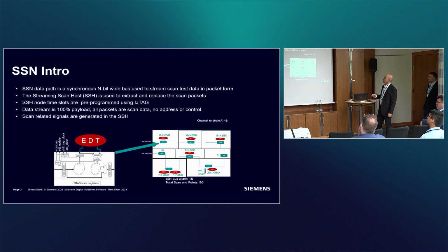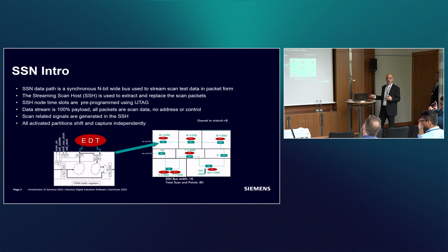As you can see, we have scan-related signals that are generated inside the SSH, here at the top. Scan enable, EDT update, all these signals are generated internally, which gives us more flexibility to control and divide and conquer. I think Ofri will elaborate more on this topic as well. Maybe this also gives us the ability to activate partition shift and capture independently, which has a benefit for power and timing, of course, from the implementation side.